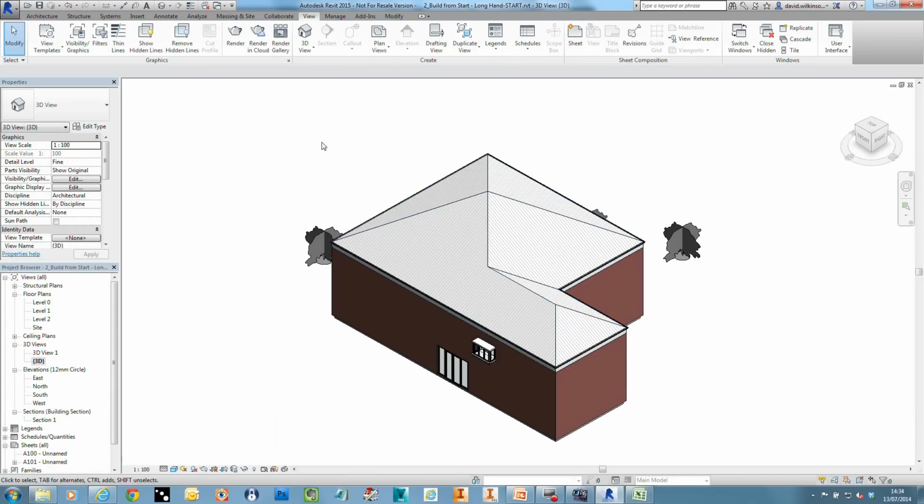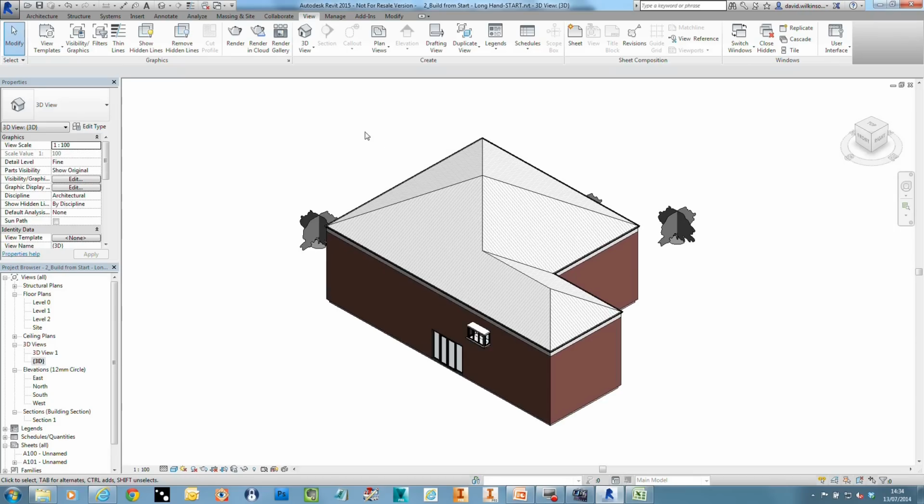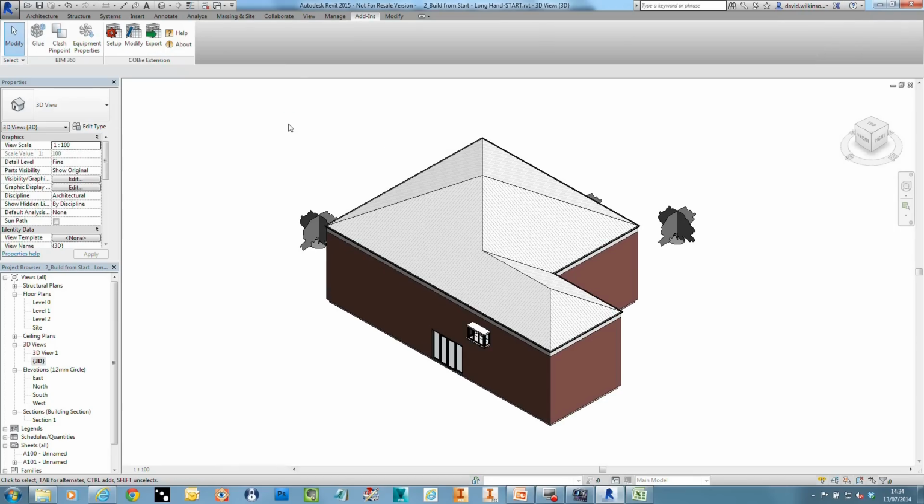Let's get into our 3D view a little bit. So there's our 3D view. We're talking about BIM really, and hopefully you've got a flavour of the BIM families. I'm going to expand on that more from a mechanical point of view in a moment. But within Revit, all we're interested in doing is just bringing those families in and placing them into our model. The families should have the right information embedded. We can embed that through Revit if they haven't, but generally you're pulling in manufacturer's detail.